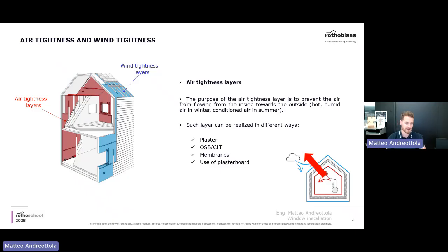If you are a designer, and I think most of you following this webinar are designers, every time you do your drawings of the building, it's important to draw these two lines. One being the airtightness line on the inside. You can draw it, for example, in red. We'll see again some examples throughout this presentation, and also the waterproofing line on the outside, thinking of all the details. Actually, I've been working for many years as a structural engineer, and in all the designs that I've seen in my career, let's say, I've seen many details for the structural part, so connections and so on and so forth.